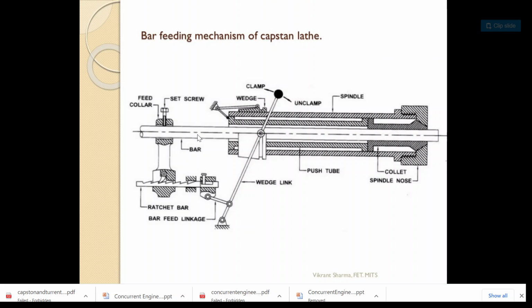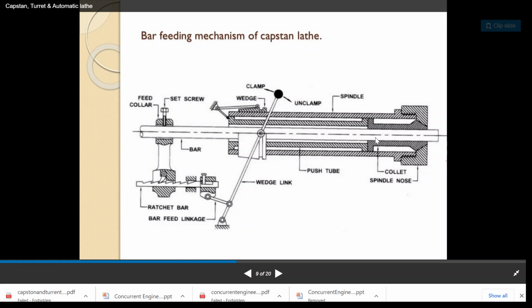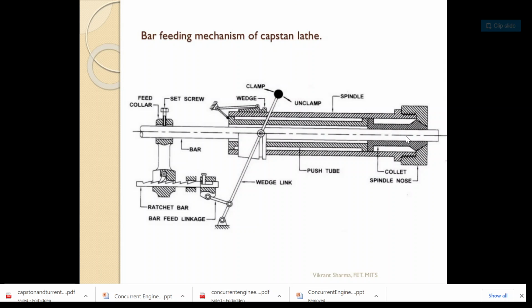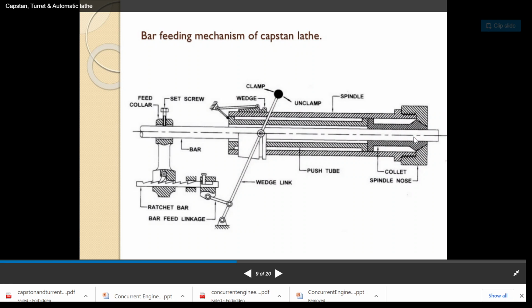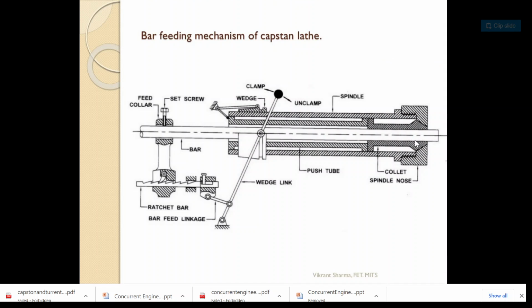That means, for example, if the cylindrical workpiece is used for manufacturing bushes of equal sizes. So once you feed this long rod, you can start the machine, and after completing the entire operation of a specimen or a product or job, that will be separated from the raw workpiece or the job, and the next operation will start, and that also will be completed. Like that you will be getting many number of identical components.